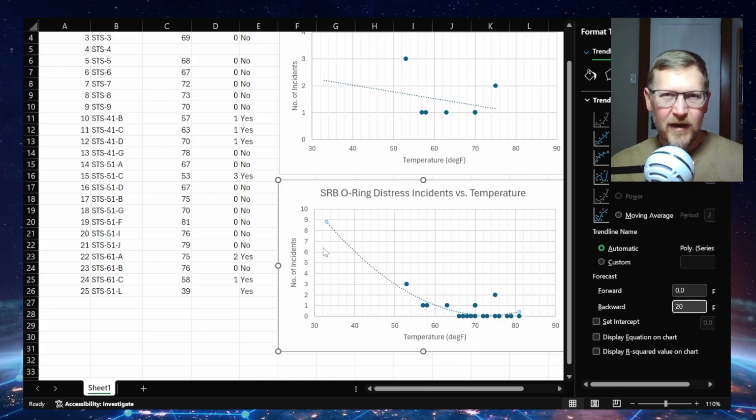It doesn't make it very obvious, whereas if you set the scales the same, the stress concentration areas can be very clearly identified because they're using the same color scales. In other cases, I've seen folks using very different scales, and it makes it really hard to even understand what you're comparing here, right?